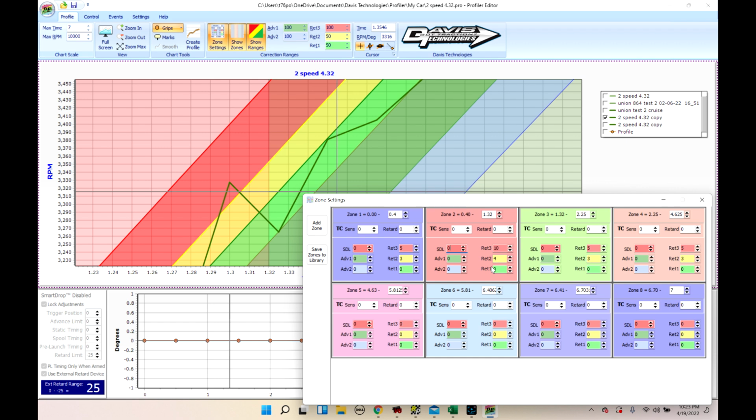So we're, in essence, causing a misfire. And if you've ever dealt with a misfire down track, if the thing starts missing, it slows down dramatically, okay? It kills power. So what Smart Drop does is it shuts off one cylinder or up to 4 cylinders in an order in which it won't load up on fuel and hurt the motor, okay?